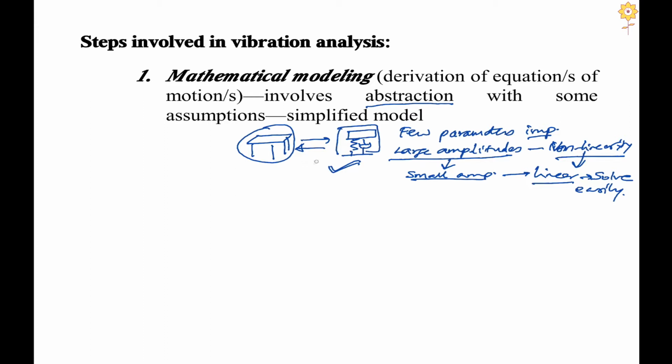So I can get n number of such models created with different degrees of freedom. So as a design engineer, to start with any problem, I start with a schematic model having the least degrees of freedom. Say it is only 1, something like this. So only one mass represents all the masses in the real system. Only one spring represents all the elastic components in the real system, and only one damper represents all the damping coefficients or dissipating elements in the real system.